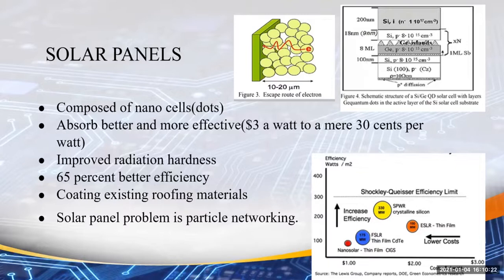Integrating a high quality film of silicon nanoparticles improves power performance by almost 6% in the ultraviolet range of the spectrum. Another starting point for the increase of conversion efficiency of solar cells is the use of semiconductor quantum dots, which is QD. By means of quantum dots, the band gap can be used to convert also longer wave light. Potential advantages of these cells are higher light absorption in the infrared spectral region. Another important property of dots is being a heat carrier.